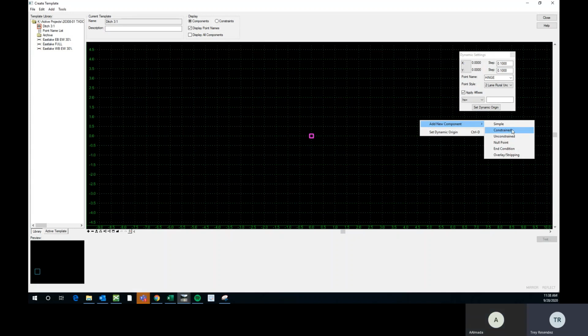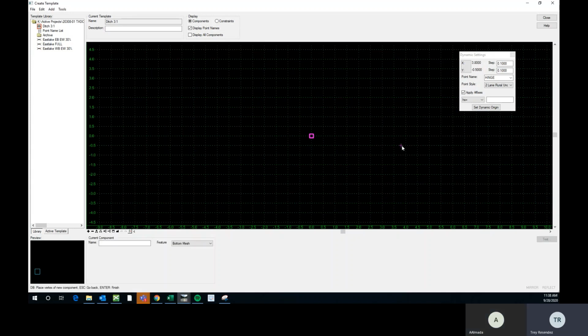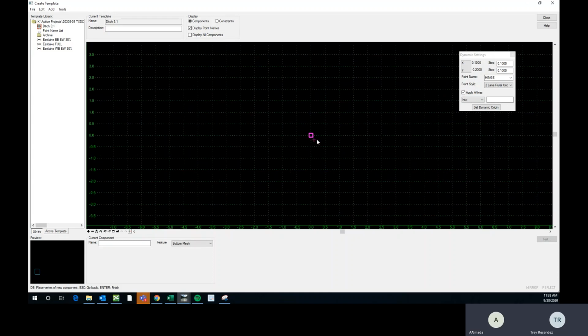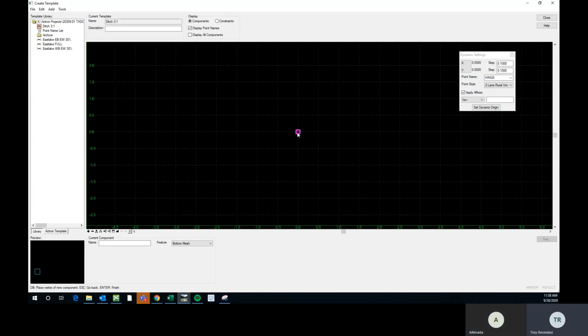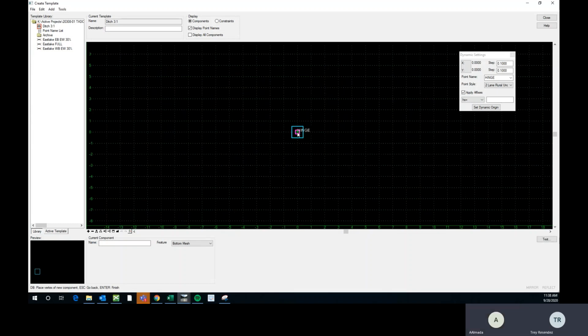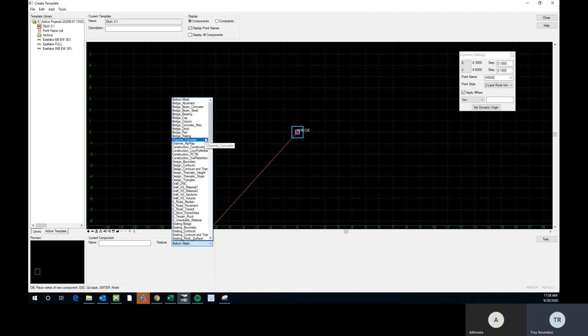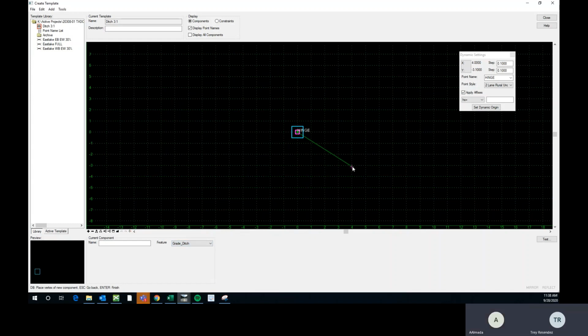You can do constrain, and then we're just basically going to make a triangle. So here's going to be one of the hinges, and pick an arbitrary point, and we'll get that fixed later. I'll do close shape, and then we'll pick an endpoint.